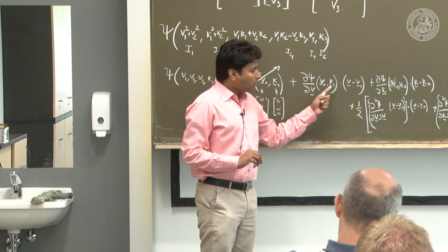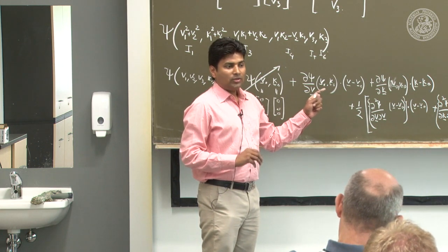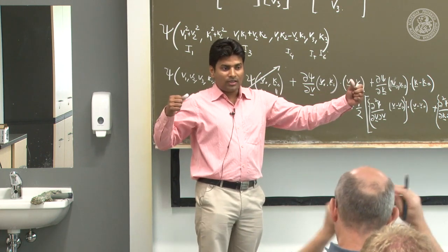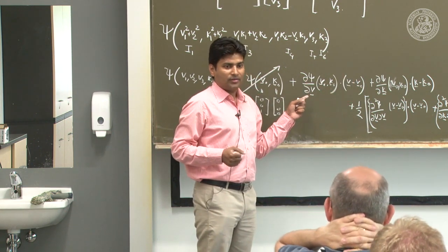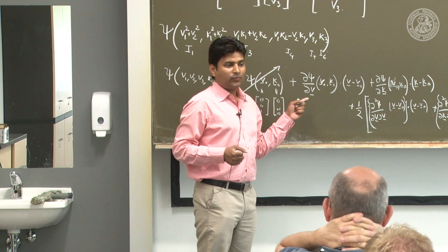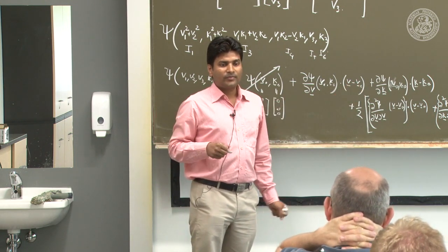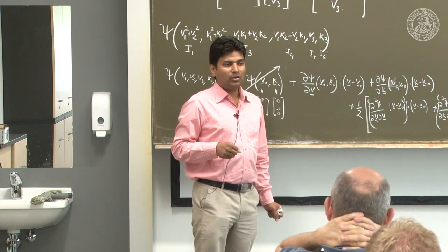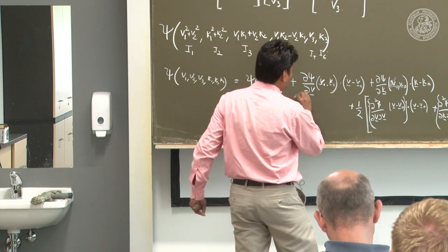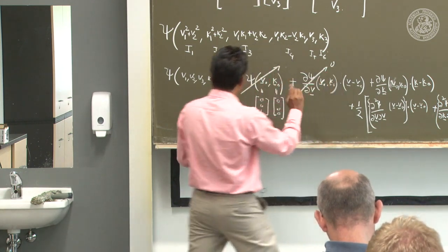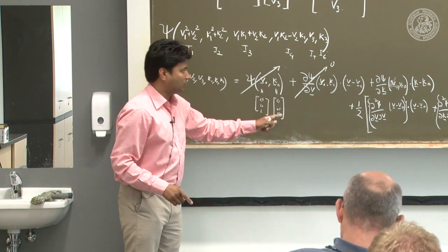And if your V0 and K0 are the strains corresponding to straight state, what will be del psi over del V there? What is the force in the straight state of the beam? If the beam is not deformed, what's the force in it? It's 0. So that's also gone. If you are expanding about V0 equal to 0, 0, 1 and K0 equals 0, 0, 0.